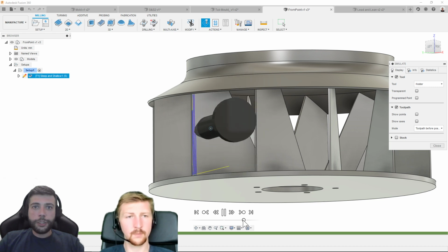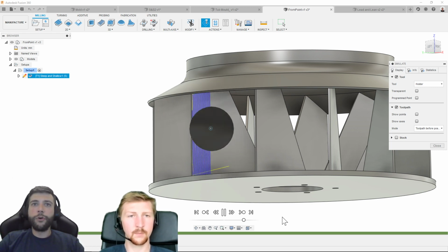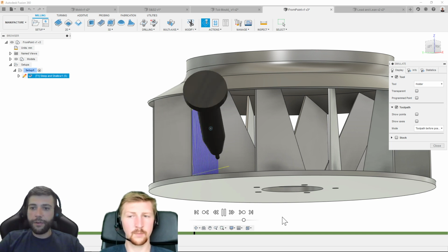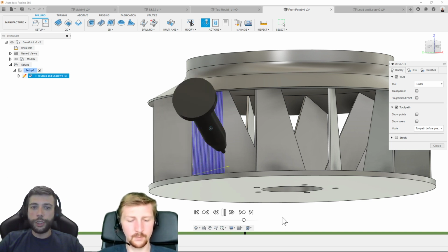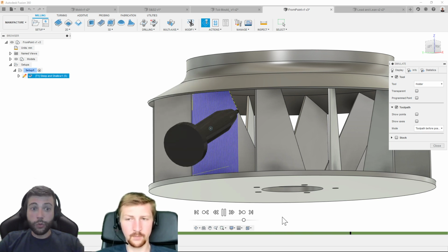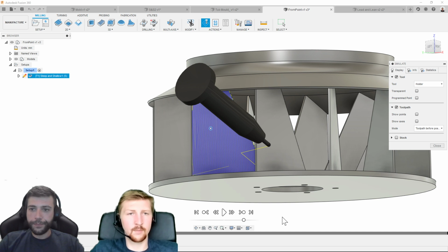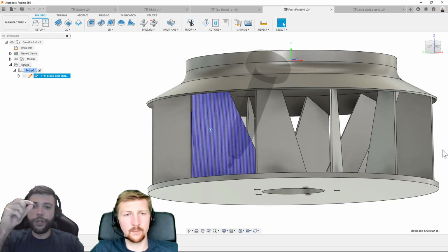Let's speed it up a touch. If you notice, the tool runs back and forth, always maintaining that given point as the reference when changing its tool axis. Again, that to me is a game changer. To do something like that before would have taken substantially longer, I would say. And imagine how many things you can do with just a point as a reference. Again, spherical components, freeform surfaces, pretty much anything where you can envisage a point being the driving element for the given toolpath.